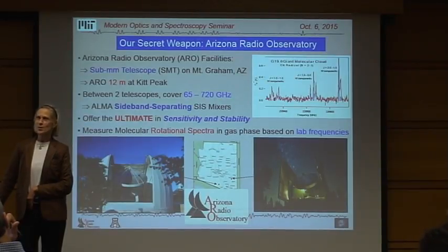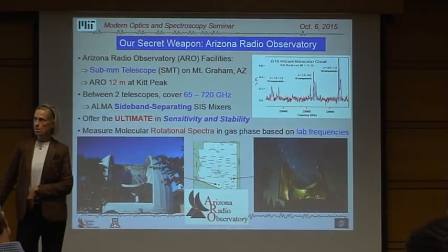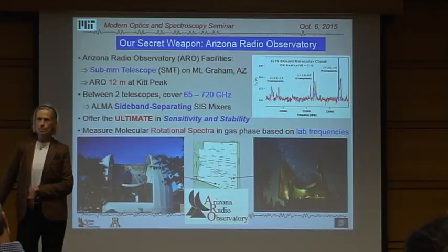When I try to heterodyne something, we do it in our lab. If we don't have a nice phase coherent source, it will not work. Yes, we have a nice phase coherent source in the local oscillator. No, that's your oscillator, yes, but whatever it's interfering with also needs to have a well-defined phase, and that's the question that I have. At least that's the way it works on the lab bench when we do this sort of detection. Yeah, I understand what you're saying. I don't have an answer for you off the top of my head. Okay, we can talk about it later.